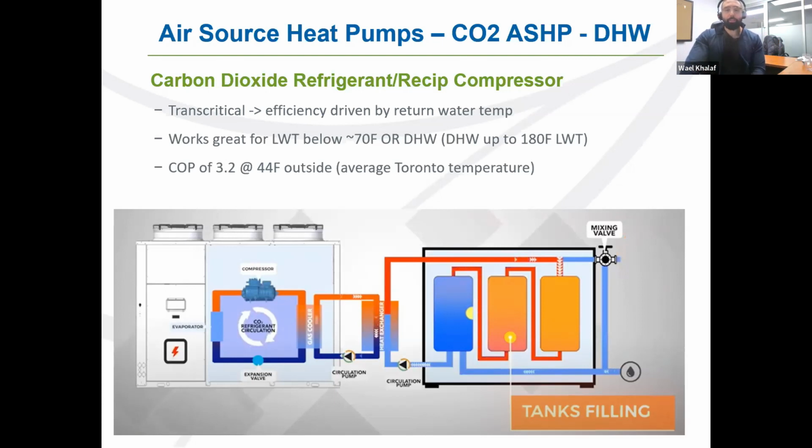And now, without getting into too much detail, whenever we're looking at heat pump applications for domestic hot water production, we can really benefit from intentionally stratifying some of the storage tanks, as you can see in this image. So the tank that's closest to the hot water production will be the coldest one, and the one furthest will be the warmest one. And we have different ways of stratifying these storage tanks, and the quantity of storage tanks will depend on how much space we have.